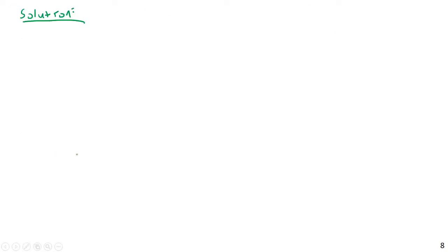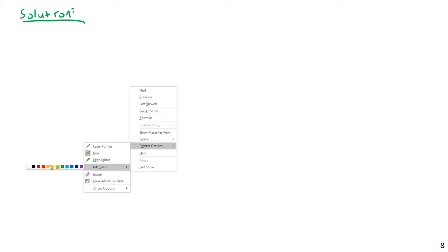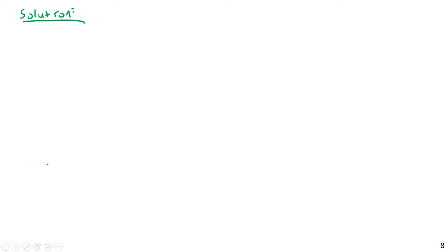Okay. So let's do that. Solution. Well, I'm just going to go down my list, and what I'm going to try to calculate for each of these is a line load. Because we are doing beam design, ultimately, I want to get some line loads, some W's. I don't want distributed loads like pounds per square foot. I want a line load, a pound per foot, or a kip per foot, something like that. So first, let's tackle dead load.